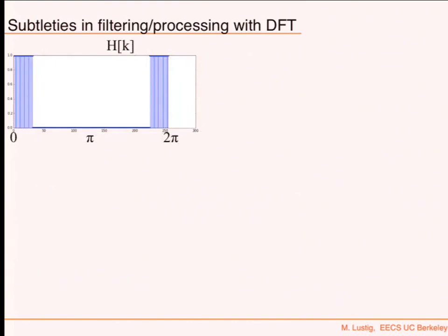So in one of the homework questions, okay, I want to low pass filter a signal. What I'm going to do is take this window, compute its DFT, and then multiply by this mask. And then this is a circular convolution, and I'm going to take the last sample, which is the valid linear convolution, and store that one. So effectively, what I'm doing is convolving with an impulse response that is the inverse DFT of that.